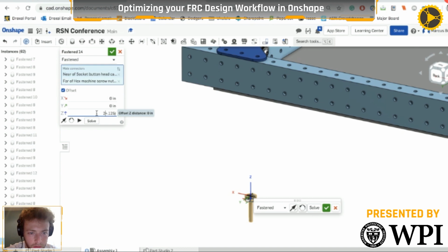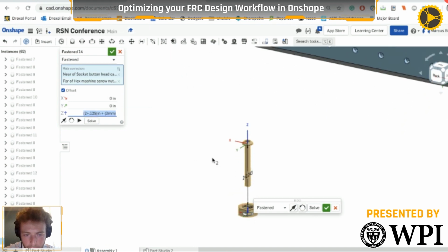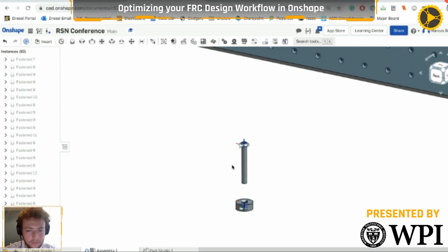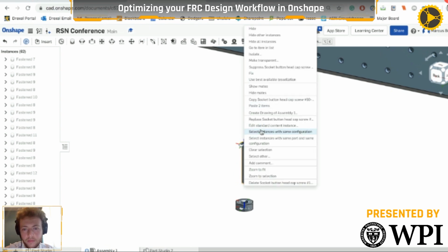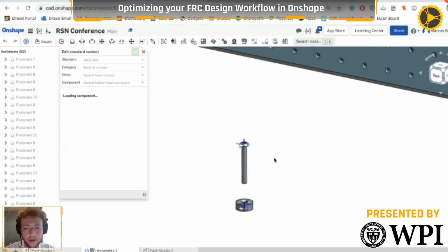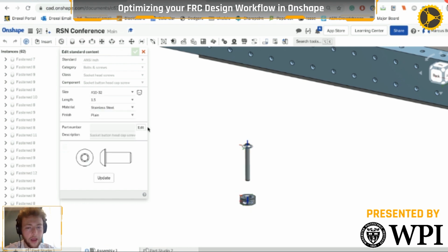These are inches. One of the cool things about Onshape, as well as many other CAD programs, is that you can do math in the fields, and then you can also work with other dimensions beyond the original. That's one of those features that when I found out about it when I was first learning CAD, that you can just do the math in the CAD software, it was a huge sigh of relief for me. Yeah, it's awesome. And you'll notice here I made a 1.5 inch bolt, which is simply wrong. So 2.5, maybe that.